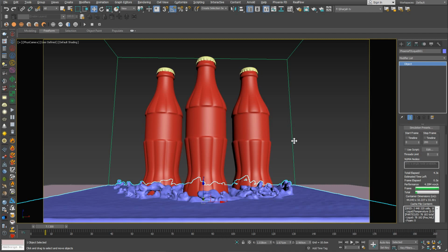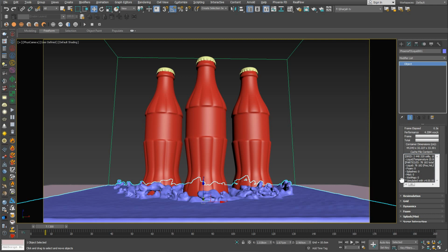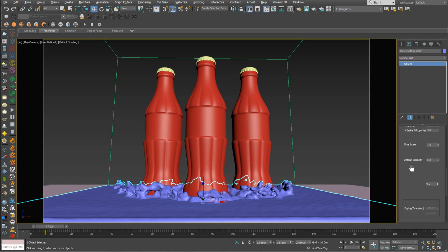This is one. The second thing is that when you change the steps, you also get different results. If you go here to the dynamics, and increase or decrease the steps per frame, sometimes we get a different result, because there are calculations between frames, there are collisions, and a lot of things happening inside the simulator.